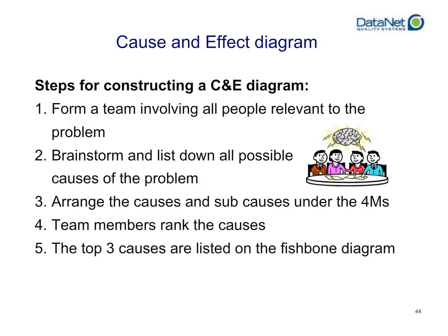The third step for creating a cause and effect diagram is to arrange the causes and subcauses under the 4 M's. That's man, method, machine, and material. You're going to find as you go through this that there's going to be some potential for either redundancy or potential to list one particular cause in 2 different categories, man or method, or man or machine, or material machine, and it could be sort of dubious. Do the best that you can to try to organize it. You will probably start seeing that there's going to be a pattern as far as where you need to focus on once you start putting down some of these causes.